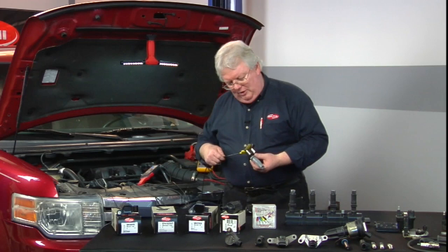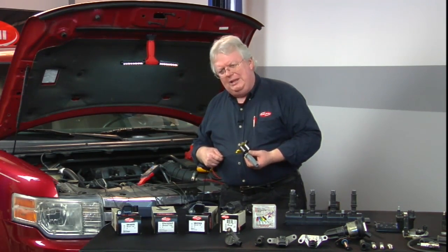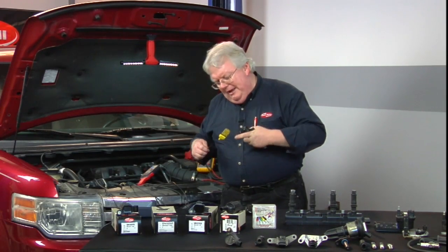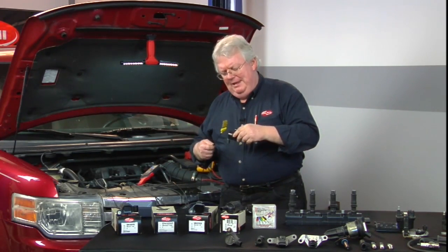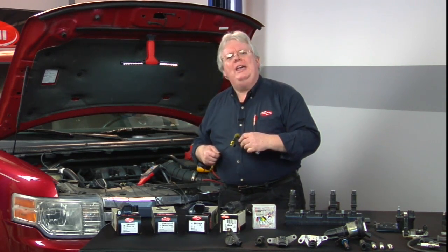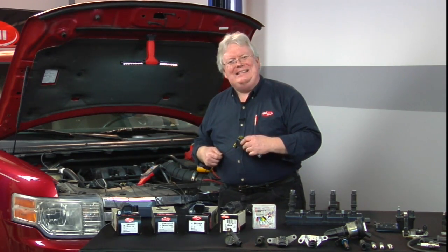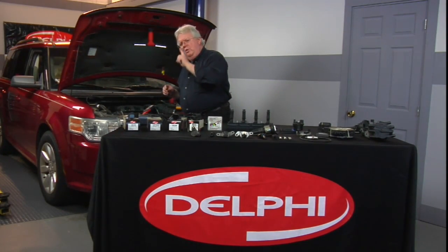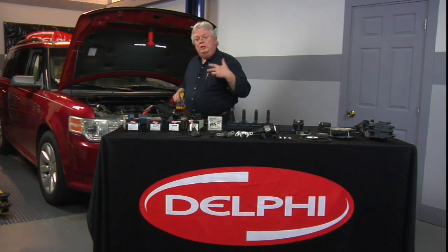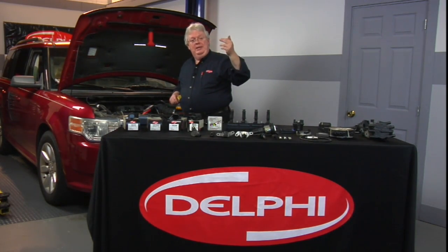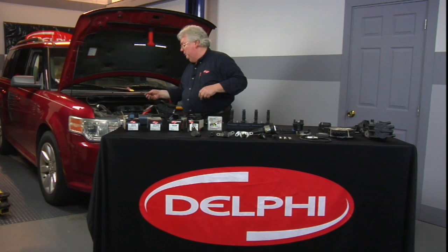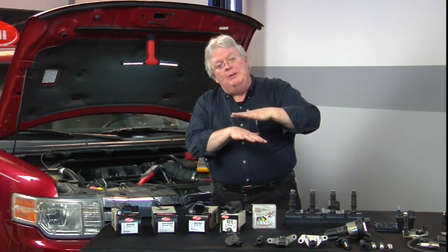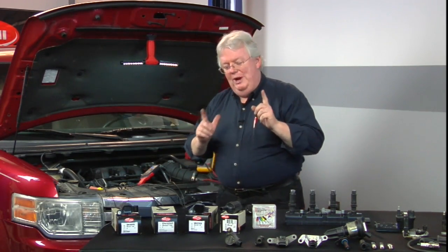Now, I actually tried it on some other coils and didn't have much luck getting a pattern on certain coils. It depends on how much insulation is preventing this little sensitive pickup from giving you a signal that looks like an old Sun or Allen machine, that secondary ignition waveform. So you can see a lot into the eye of the engine with the secondary pattern. And the primary pattern is what we're hooked to also with channel B, the red circuit. That's going to also give us the same thing, because the primary is simply a scaled down image of the secondary. So let's go ahead and start the engine.